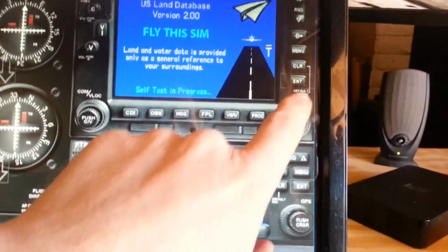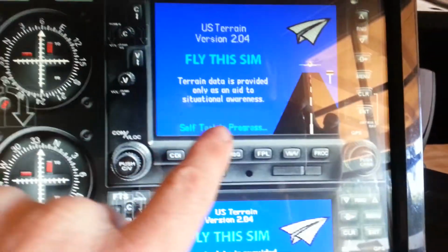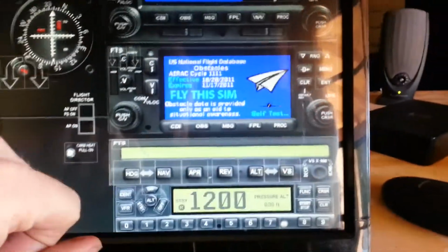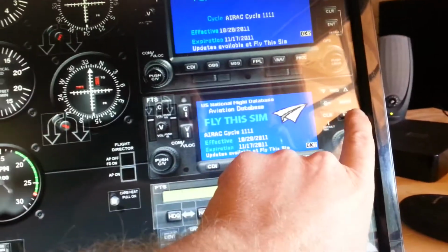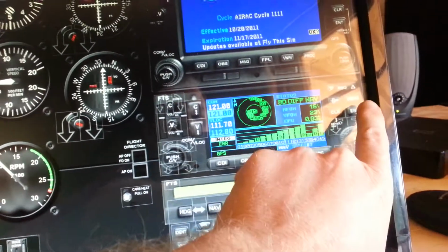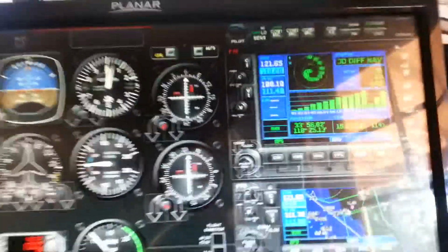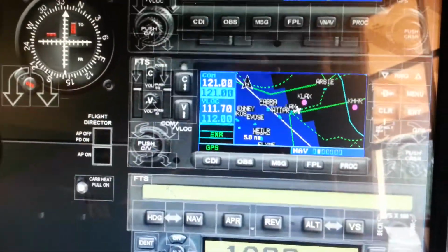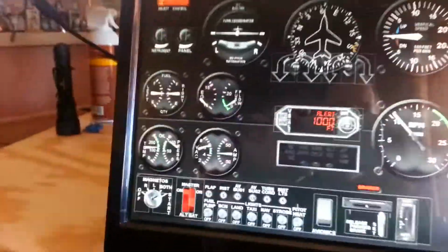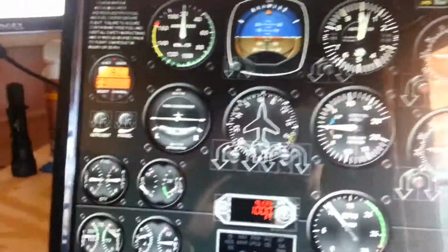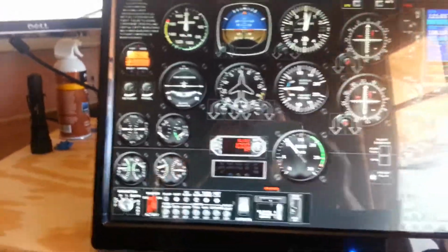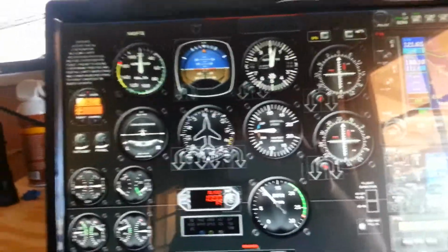You see all the gauges and dials light up. The Garmin is also ready to, its self-test is in progress. It's not ready just quite yet. But you'll see right here it says fly with this OK. You'll hit enter twice and it goes into its startup. And you'll see you've got your GPS down here, the old school GPS maps down here, autopilot down in the corner, and your regular analog gauges. So that's the way you can switch aircraft, and the panels follow the aircraft.